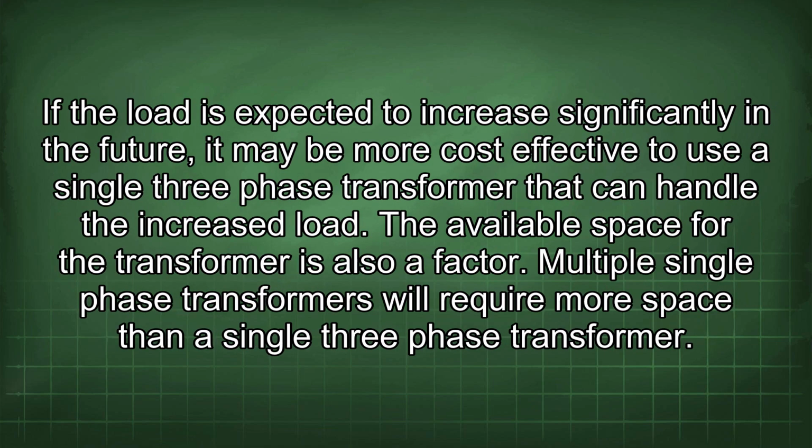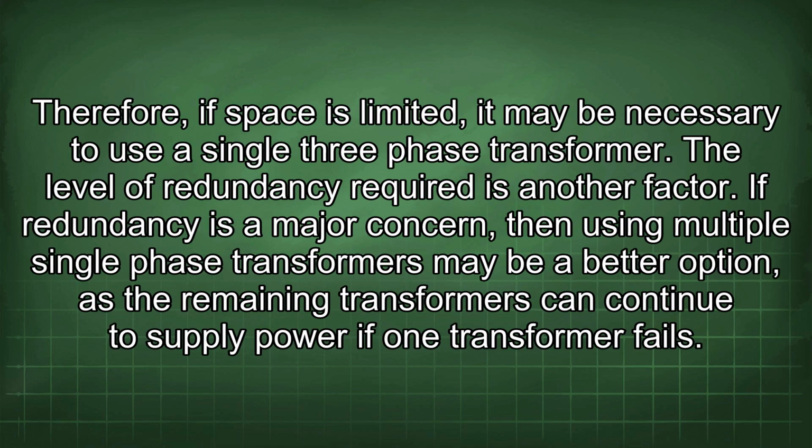If the load is expected to increase significantly in the future, it may be more cost-effective to use a single three-phase transformer that can handle the increased load. The available space for the transformer is also a factor. Multiple single-phase transformers will require more space than a single three-phase transformer. Therefore, if space is limited, it may be necessary to use a single three-phase transformer.